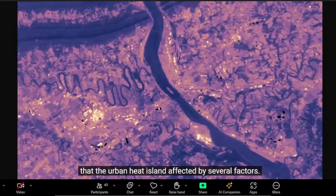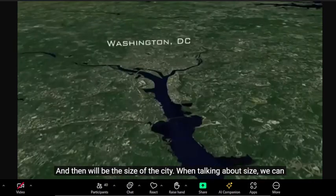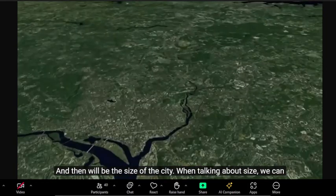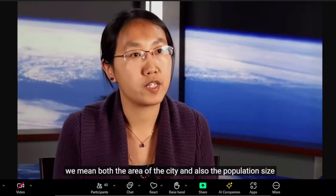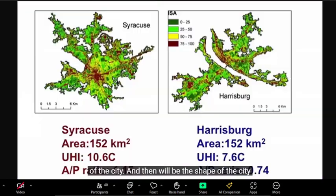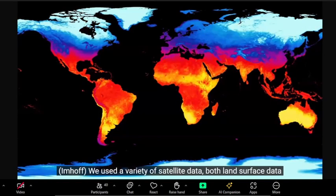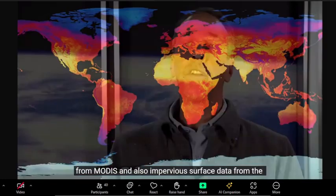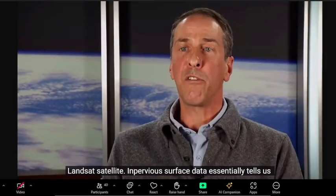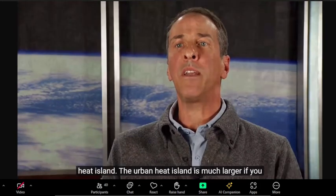The first factor will be the surrounding ecological context, and then the size of the city. When we're talking about size, we mean both the area of the city and also the population size of the city. And then the shape of the city and also the development patterns of the city. We used a variety of satellite data, both land surface temperature data from MODIS and also impervious surface data from the Landsat satellite. Impervious surface data essentially tells us how much building material is on the land surface in order to study the urban heat island.